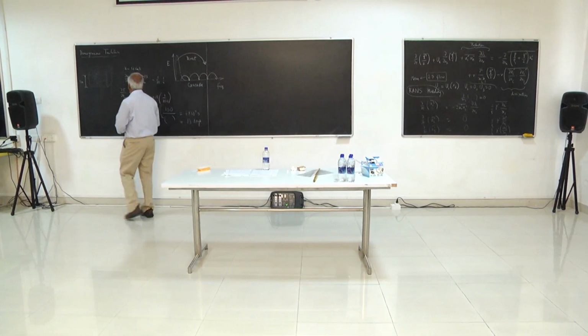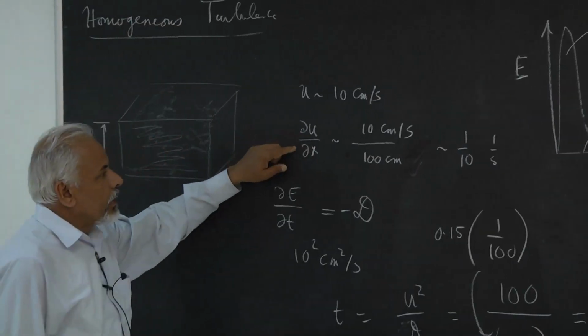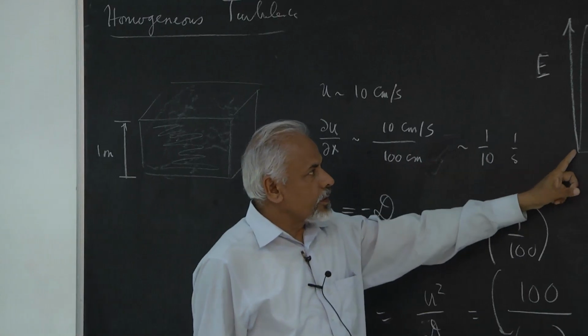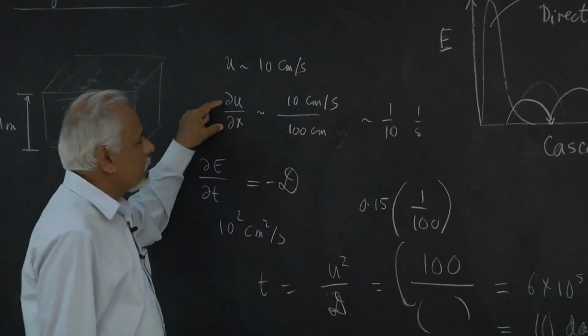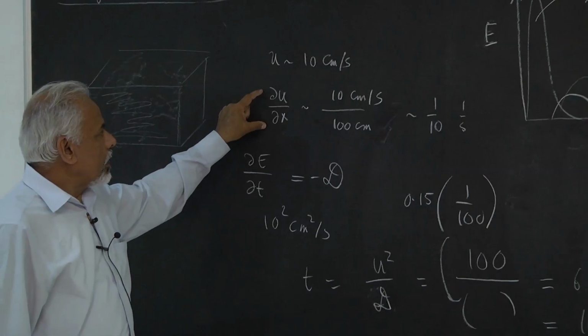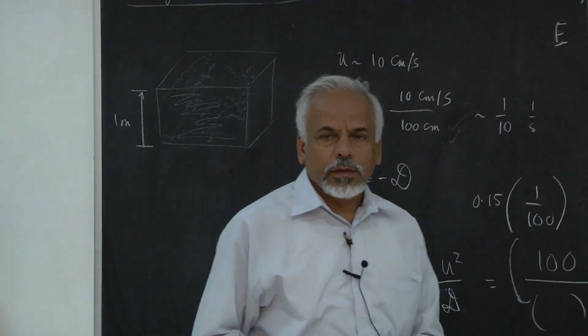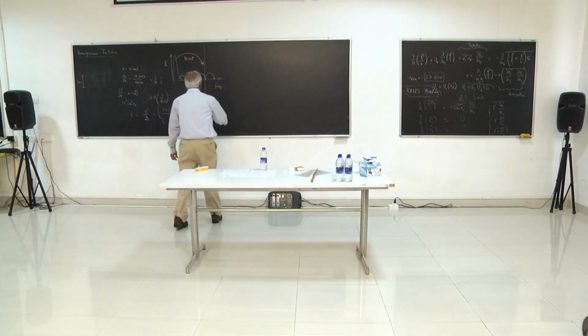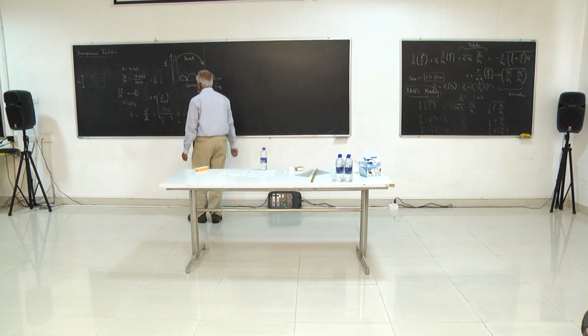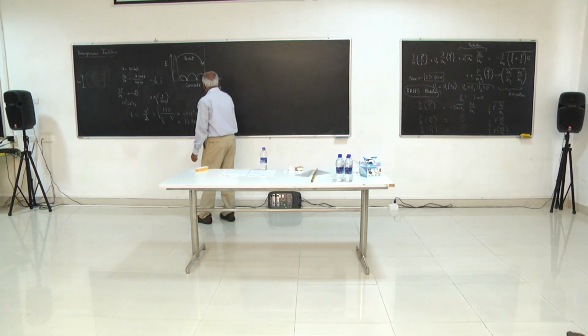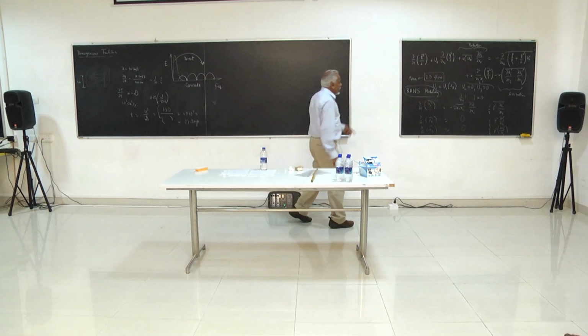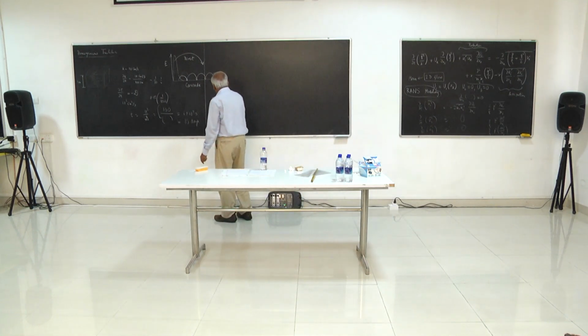As I was saying earlier, an important manifestation of this energy transfer is that the gradients become sharper and therefore dissipate a lot more energy than you can imagine by other means. Now it turns out that the dissipation term has the form nu times the square of the gradient of fluctuations, (∂u_i'/∂x_1)².